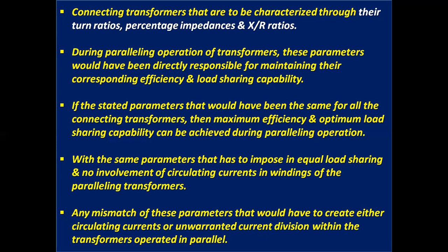With the same parameters, there is equal load sharing and no circulating currents in the windings of the paralleling transformers. Any mismatch of these parameters would create either circulating currents or unwarranted current division within the transformers operated in parallel.